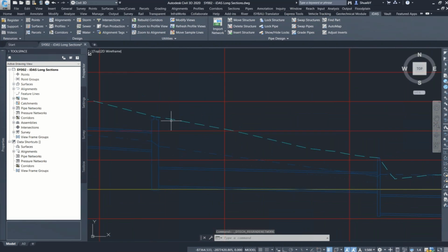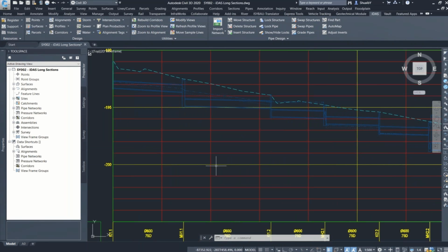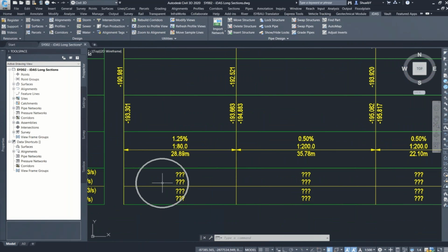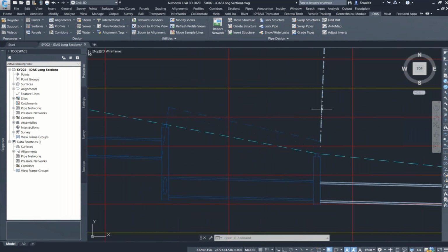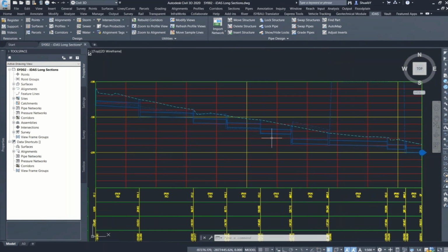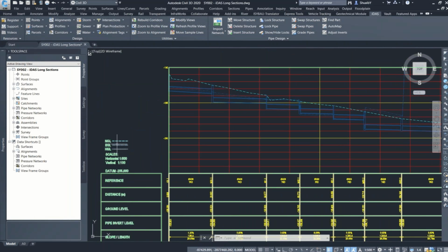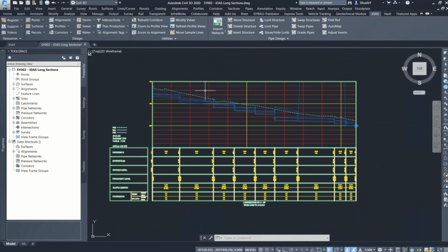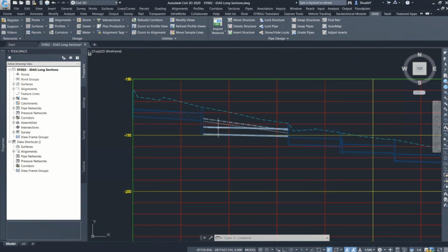And here we are. You can see once we do that, first of all, the structures are aligned perfectly to the actual NGL, or the natural ground level. And there's those question marks I've been talking about. Okay, so let's just maybe position this a little bit. Again, I said I've enhanced that just so that you would notice it. You wouldn't get it, but if you do get it, you can actually regrade your network, resize your piping, and it will be 100%. I just want to show you what you might encounter and how to solve it, rather than just giving you a perfect demonstration, right?